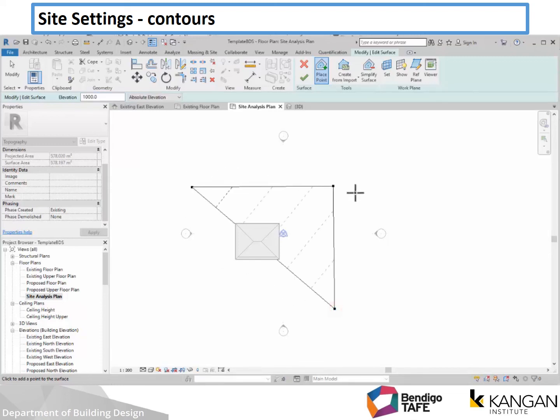You can see the toposurface starting to appear, and we've got contour lines running through as well, so everything seems to be set up okay. I'll go -600 for the next and the final point. So we've got our 4 points in there, and pick OK.